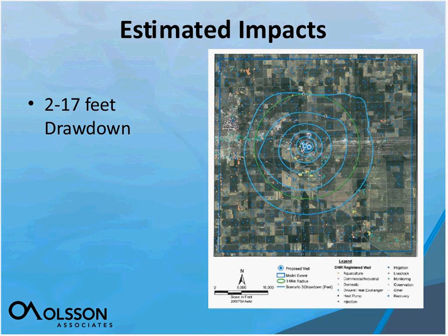The other ones, though, we did look at in detail, as I showed before in those tables. We looked to see, for the wells that showed some significant impact, whether there was another well this irrigator could use in their area, or what options they had, because some of them did have more than one well and could use the other wells as an additional water source.